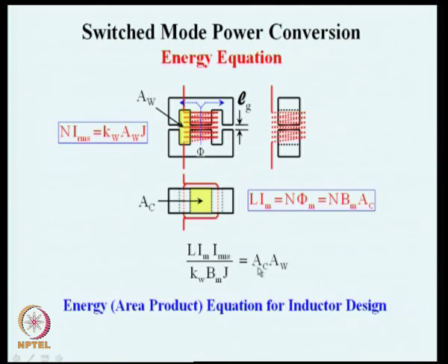What it indicates is that for any inductor that you wish to design, which has a maximum current rating of Im and an RMS current rating of IRMS, it will require a core whose area of the magnetic path and area of the copper path, the product, has to satisfy this relationship. So, if you wish to store more energy, you need a bigger core. If you need to store less energy, you can manage with a smaller core.